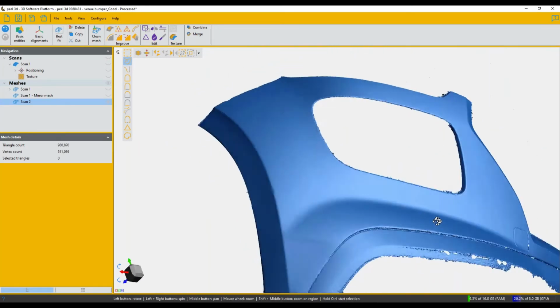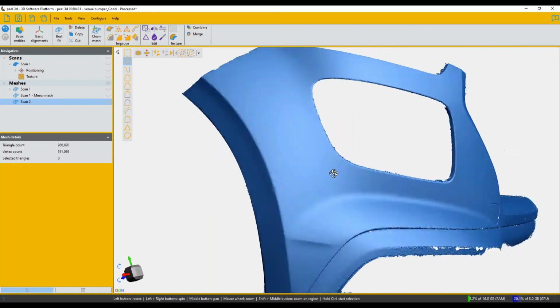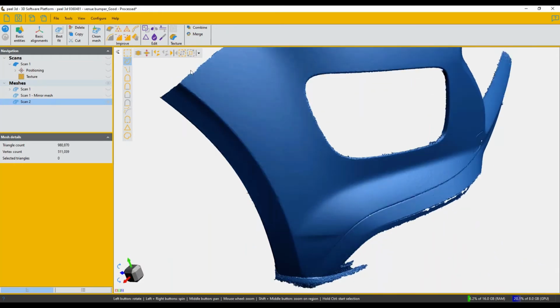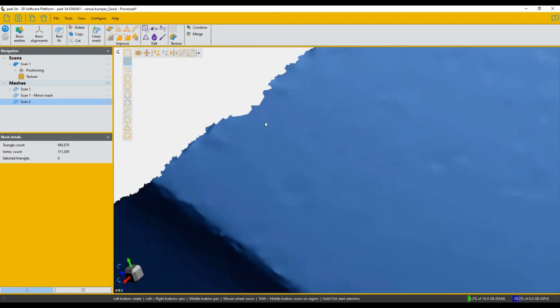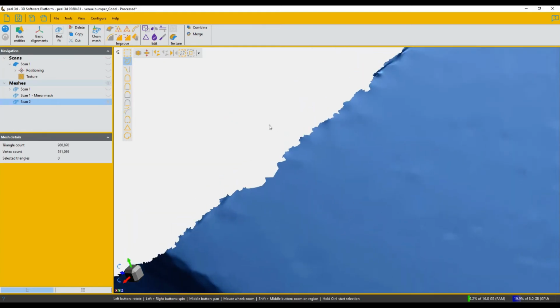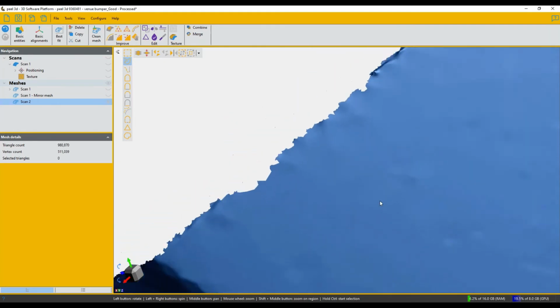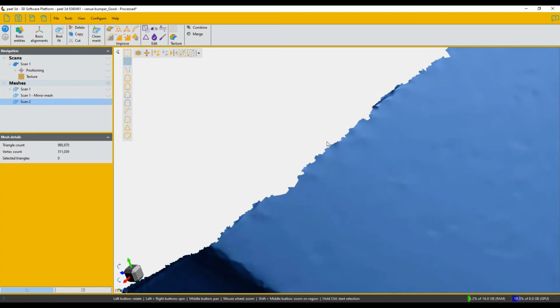If you have any kinds of holes in your mesh, you can fill those in again. As we move around our boundary, you might find it's a little difficult to rebuild some areas of the boundary depending on the curvature of the surface. So if you have a hole in your mesh, we can fill that in. If you have a hole on the boundary and as you're trying to rebuild the edge, it's sucking in your rebuilt edge too much, you can do partial fill as well.